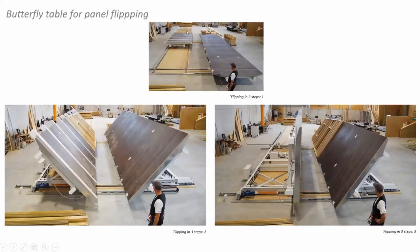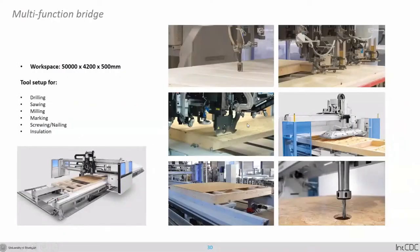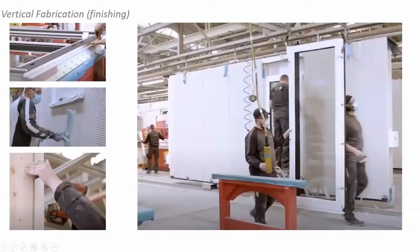So it's going to be brought over here, and then there's this so-called butterfly table that lifts this element from that side. Here they are closing a scissor and handing over the cover plate side inside to the outside, and then the step can be repeated and the outside plate can be placed. Once this step is done, both sides are covered, and the previously horizontal fabrication sequence, which had a high level of automation, is going to rotate by 90 degrees.